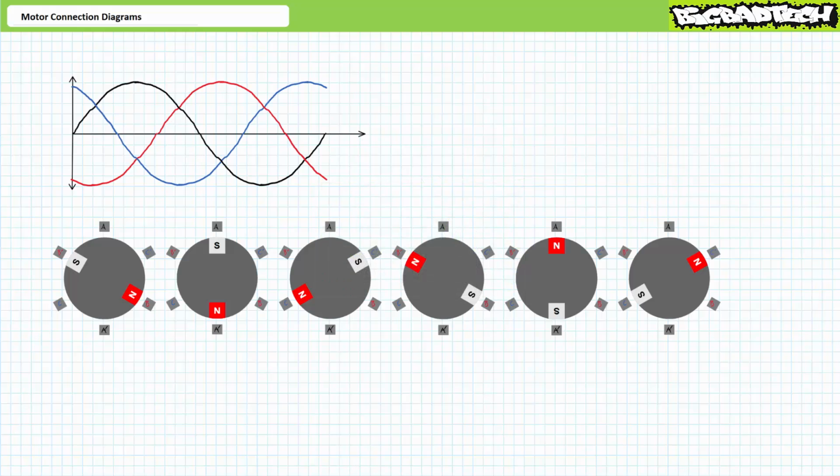You'll recall, an electromagnet is established in a coil of wire whereby the polarity of the resultant magnetic field is dependent upon the direction of current flow, and the strength of the resultant magnetic field is dependent upon the amount of current flow. You'll additionally recall three-phase AC synchronous and induction motors are powered by a rotating magnetic field in the stator, where the physical placement of windings around the circular perimeter of the stator, and the order, frequency, and polarity with which these windings are energized determines the direction and speed of the rotating magnetic field. Swapping applied phase sequence of any two phases would see the motor reverse direction.